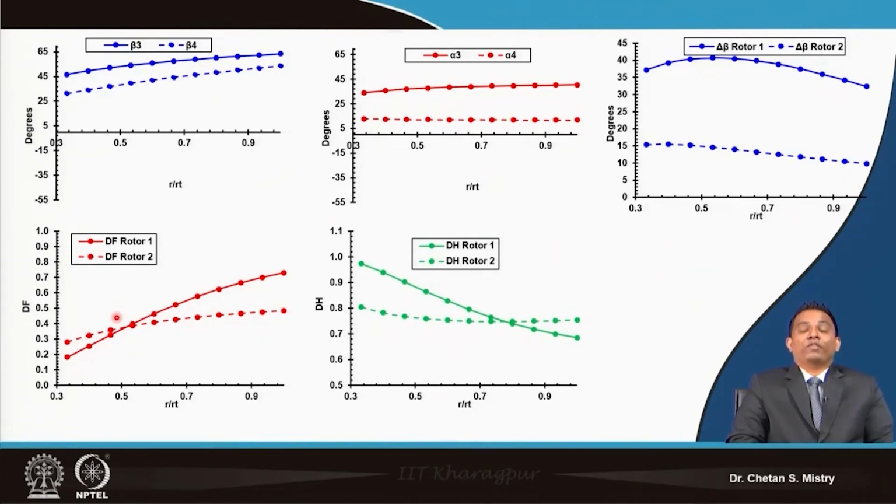Okay. So, when we are doing our design for contra rotating fan, you need to design your rotor 1 nicely. Just finalize all parameters using your Excel sheet program. Once you are confident with that, then you go with the design of rotor 2, because they are interrelated. Your small change for rotor 1 may bring more change in rotor 2. So, be careful about these aspects.